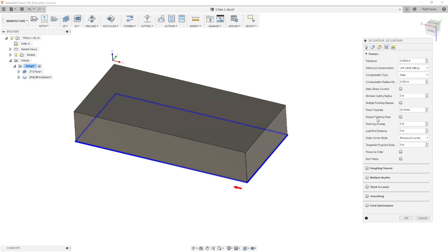If you have a cutter that's under heavy load, when it does its first finish cut, it may flex, a real flimsy tool. So a repeat finish pass would move it with the same exact numbers, just go back and do it another time, and that cutter, being under less load, may shave off just a little bit of material based off how it was deflecting the first time it came through. We don't need that. We're going to skip the finishing overlap.